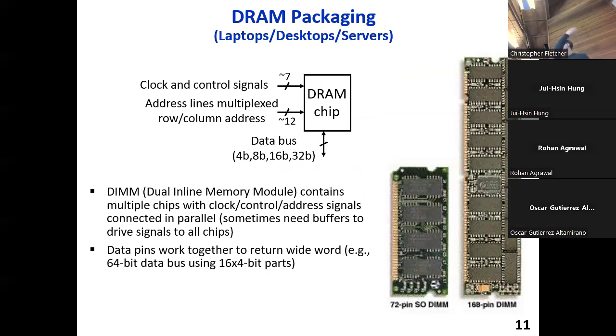Okay, so this is the whole picture of DRAM. One other note here, going back to the previous question on N plus M address lines. Again, going back to the DRAM philosophy of maximizing density potentially at the cost of access latency: if we're able to make things more dense, we're willing to slow the DRAM access time down.